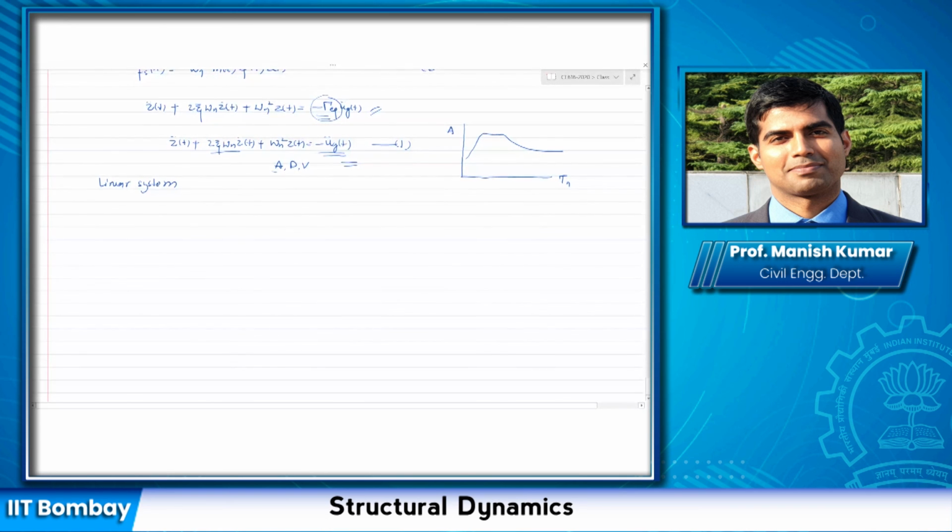So what I'm saying is, the response spectra is given for this expression. Now, for the generalized SDOF system, I need to find the response to this, and it would be nothing but whatever the response to this SDOF system is, multiplied with this factor here, because that is the factor that is multiplied to the excitation. So let us say it is A, D, and V, as peak pseudo acceleration, peak displacement, and peak pseudo velocity.